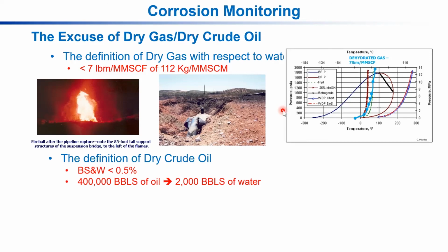Then comes a very specific property of the crude oil, which is wettability. Which one is wetting the pipeline? Is it the crude oil or is it the water? There is research going on, or there was research going on by PRCI defining what is the wettability and how can we measure that wettability of the crude oil to see which one is going to be affecting corrosion.